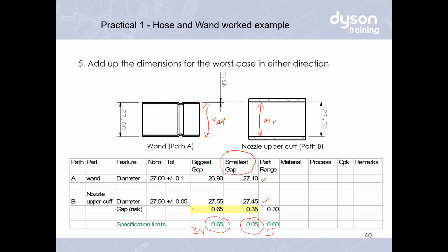You're asked to design component A and B. The first job is that A is going to be assembled to B. The first thing you do is ask what forces will be accepted by the customer to insert A into B. So you do a study, and you find that 3 to 5 Newtons is the range where the customer will feel happy and will not complain.